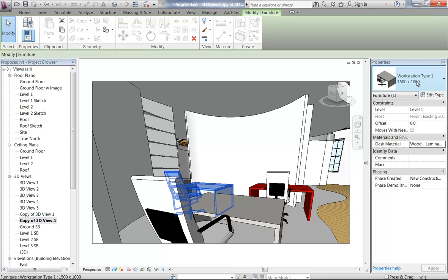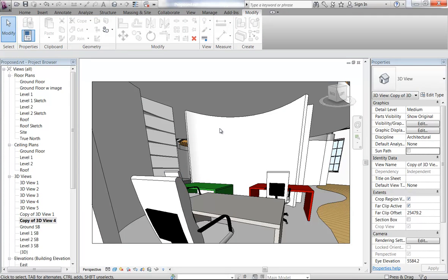I was going to do a bit with 3ds Max, but I think I'll do that next week. As long as you've assigned a sensible name for your materials and you've broken them up in a sensible way, then no matter how you're going to render them, whether it's in Revit or 3ds Max, you can easily assign the materials because you've got the name there. Even the appearance you can set up later, but it's most important that you get the assignment and the way it's organised set up when you first start modelling everything, or even after you've modelled, if you go back and set that up, because if you're trying to break it up later when you've got a huge project, it just takes too long.